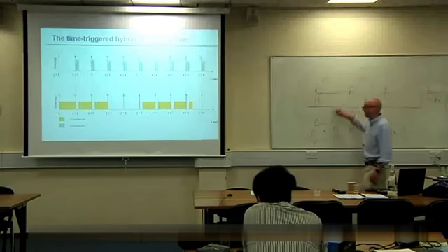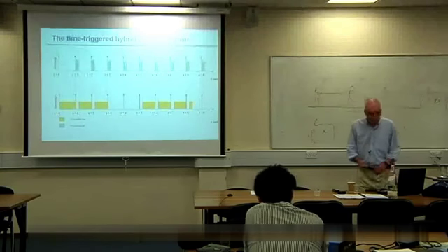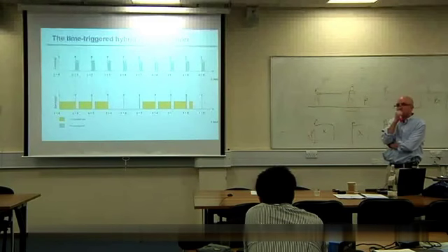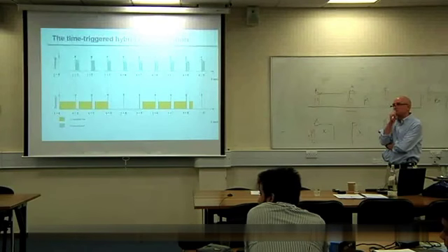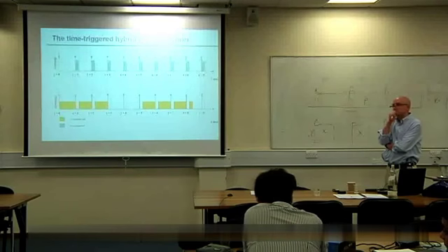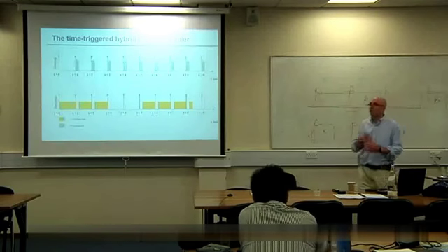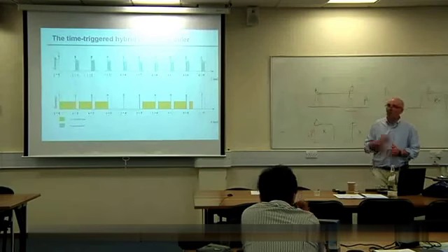Let's make it 0. You can tell me how to make the jitter in that identical to the jitter in this, still using interrupts. How do you do it? Synchronize the interrupt with the tick, so that task X runs at every interrupt and the tick corresponds to that. Well, that's exactly what happens here. You have to stop a bit before that. Okay, that's exactly what I want to do. Tell me how to do that.